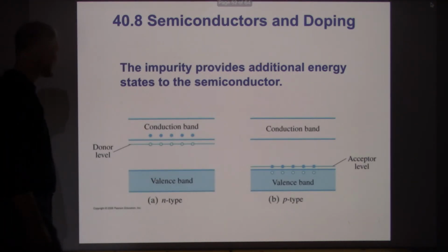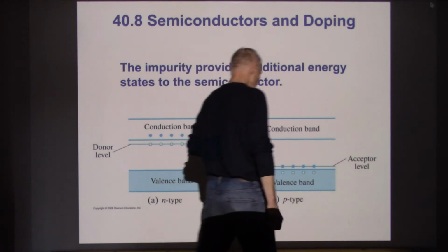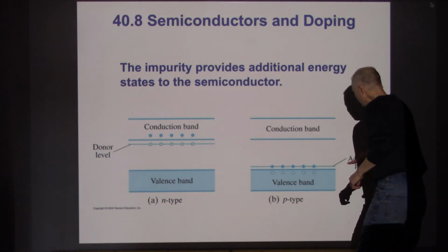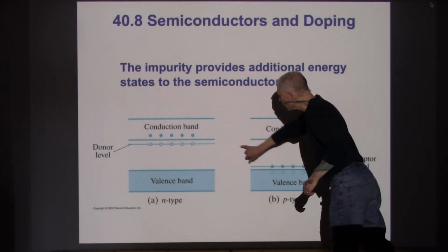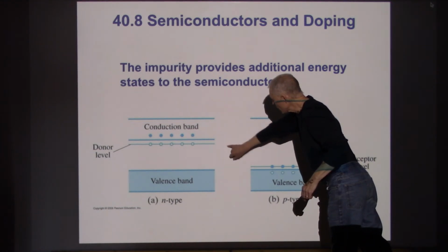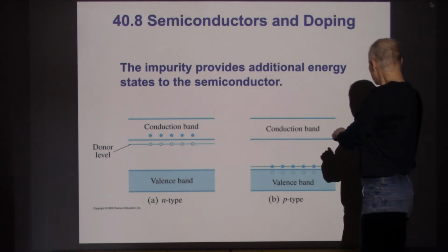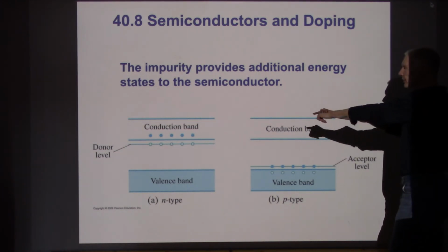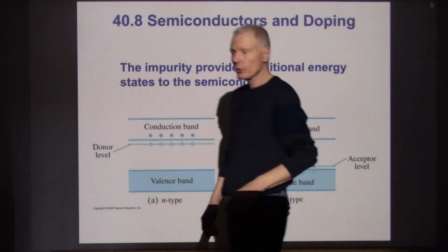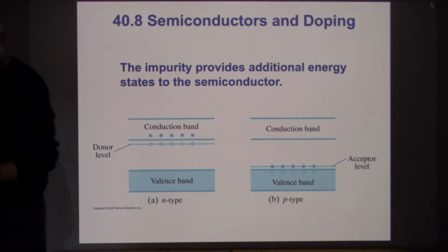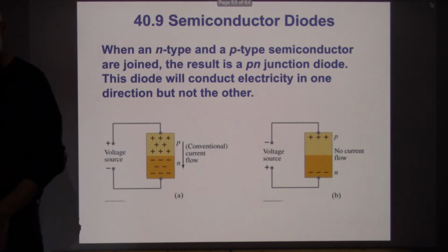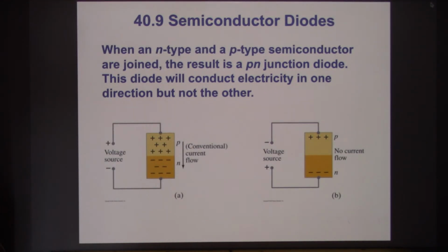And so what happens is this: when we reverse the direction of the electrons and push electrons into here, well, this is still quite a gap. And so the electrons are not easily able to move from the acceptor levels into the donor levels. And as a result, a device built out of two layers, one of each of these types of material, favors one direction of current over another.